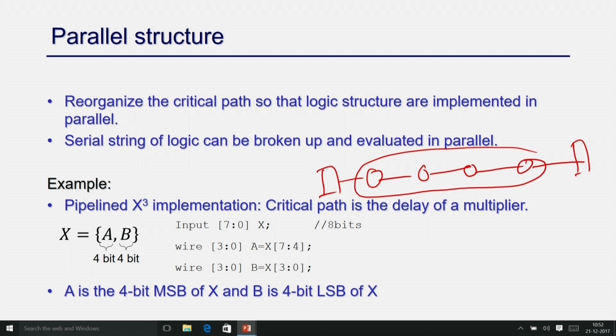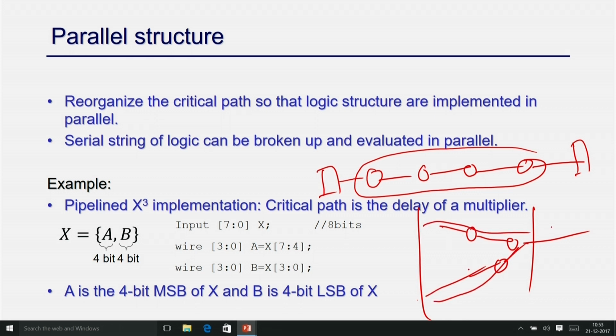But at certain times you can change your design as a whole. You can change your logic a little bit so that you can actually parallelize these things. For example, you can do something like this here, so that the delay, which was earlier 4, becomes maximum 2. So you can do certain kinds of optimizations, but this is your design choice and the expertise of the designer. It is not possible in all places, but at certain times you can do that.